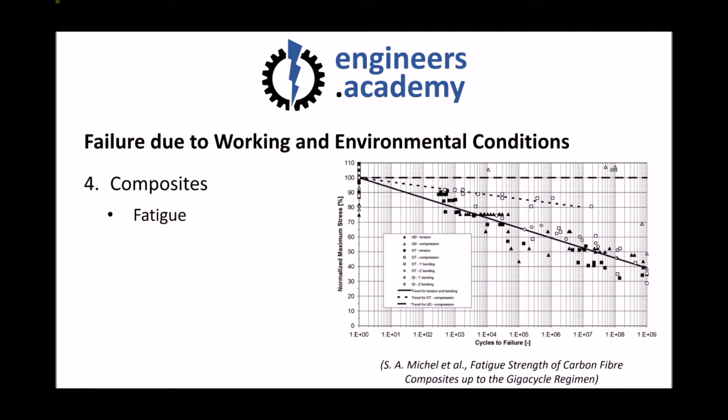But what you'll probably notice is that we don't have a fatigue limit. So in metals, if the stress is suitably low, then we can assume that the material has an infinite life, but we don't see that with composites. It means that any degree of stress can eventually cause fatigue.